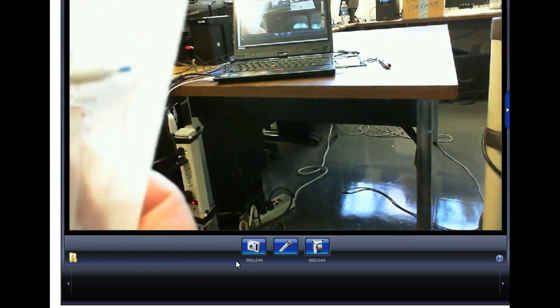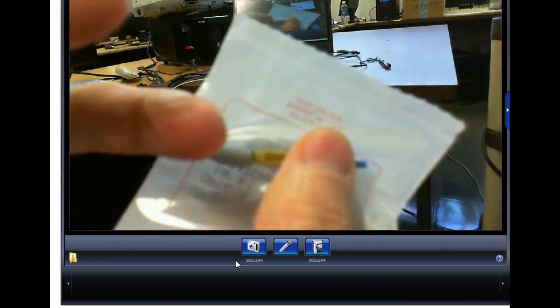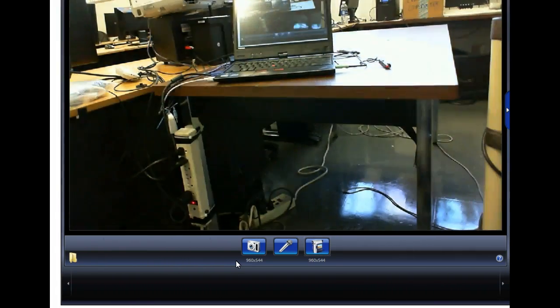So this is an ultra splice. I'll pass this around. This is a semi-permanent splice, which means we can remove the splice without recutting the fiber. With a mechanical splice, a permanent fiber splice, like the FiberLock, if something happens to the splice, you've got to cut it out of the fiber.